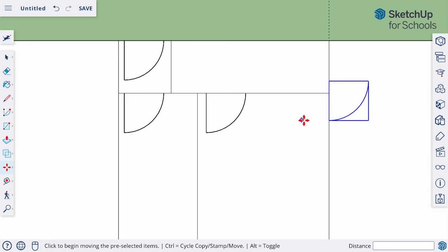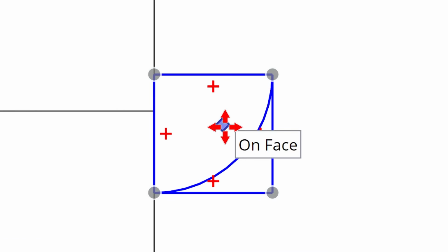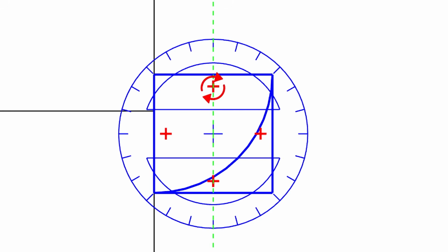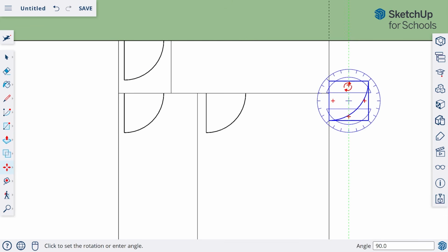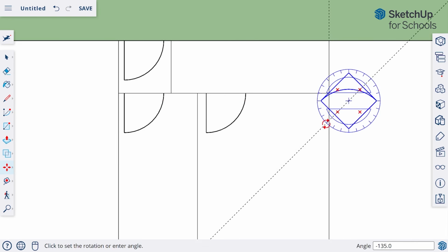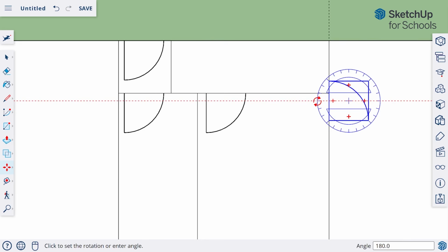The Move tool, as you hover over an object, has these 4 plus signs. And if you hover over one of those plus signs, you'll see a built-in rotate appears on your cursor. When you see that rotate active, go ahead and click. By clicking, it activates the rotate tool, and now I can dial this down till I get to here. Try to put your cursor somewhere along one of the ticks. That way it actually dials in. You can feel it click.